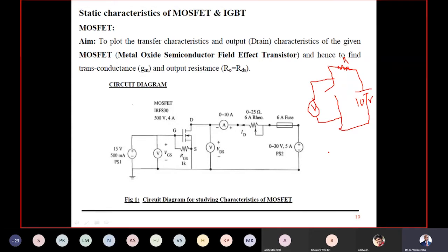10 volt. Pardon? Louder, a little bit louder. 10 volts. Perfect. 10 volt, because the switch is open now. When the switch is open, the voltage drop of the switch is nothing but the supply voltage, 10 volt. When the switch is shorted or turned on, voltage is 0.